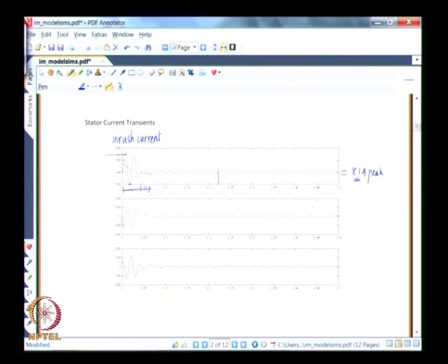Similarly, on this side you can again see that there is another offset which decays down to 0, and here perhaps there is no offset, these are two identical almost 100 ampere here and 100 ampere here, the offset if at all is there is quite small. So, initial offset will be there because you are switching on to an RL circuit with initial conditions as 0 ampere everywhere. So, to accommodate the initial condition, the system introduces an initial offset which then decays down to 0.